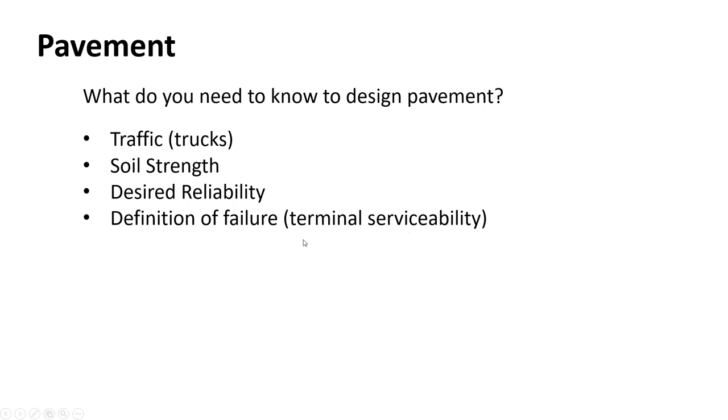Again, on an interstate or an arterial road, we usually pick a 2.5 as our serviceability rating out of 5. If it goes below that, we'd say it's failed. It's not a good road and you can't maintain speed, and it damages vehicles and sometimes can be a hazard as well. On a small road, on a local street or a county road, we'd often say our terminal serviceability number is 2 instead of 2.5. We can allow it to get worse. People expect more potholes on those side roads and those small roads, right?